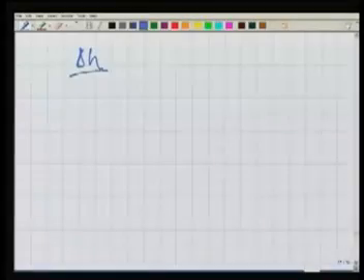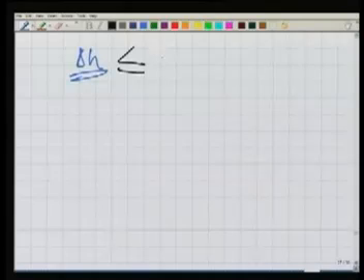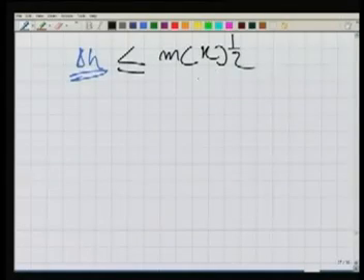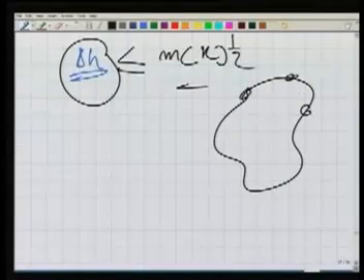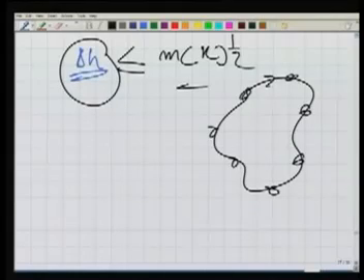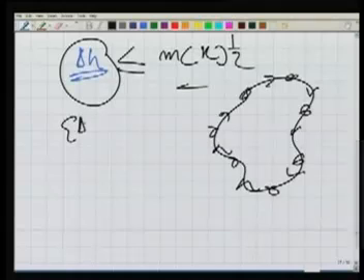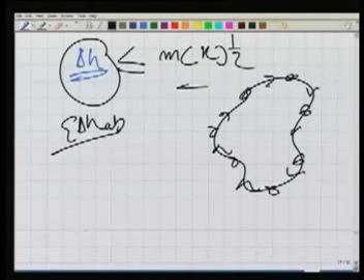Well, the closing error, let's say delta H is the closing error. If it is less than these values, K raised to power half and the other one, we will accept it. Accept means we will say, okay, there is no need to revise the survey, to go to the field again and do the survey. But within the network, because we are finding the difference in elevation between all these points, when we find this sigma delta H, the difference, it should be 0. It is not 0, but in the field it should be 0.